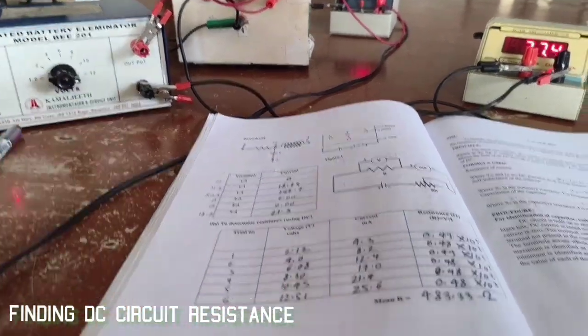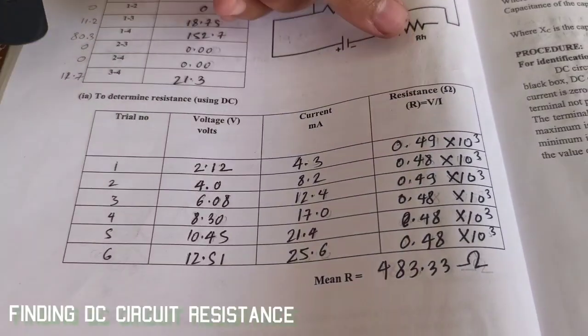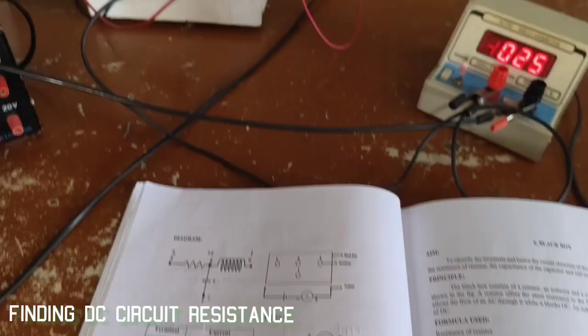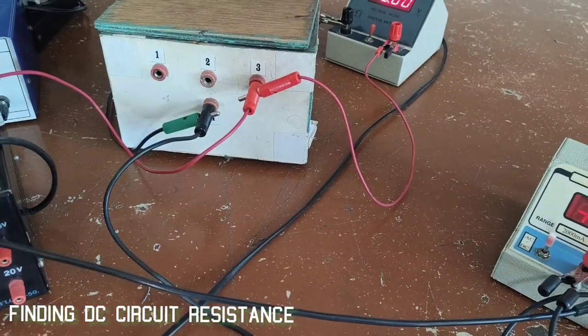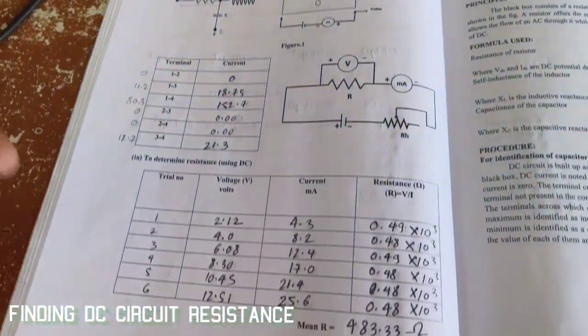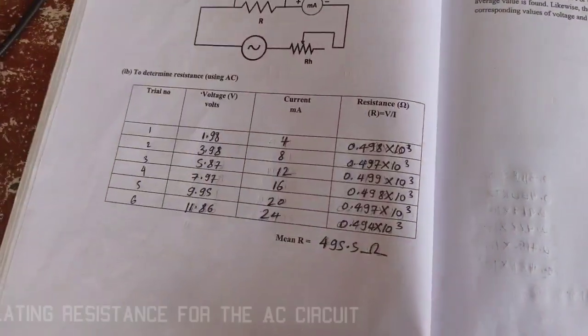And once you get the values, you have to basically use Ohm's law to calculate resistance. Another important thing is that you have to make sure it was connected to the resistor branch of the circuit. So 3, 4 was our resistor, so I've connected it to 3, 4 while finding the resistor.